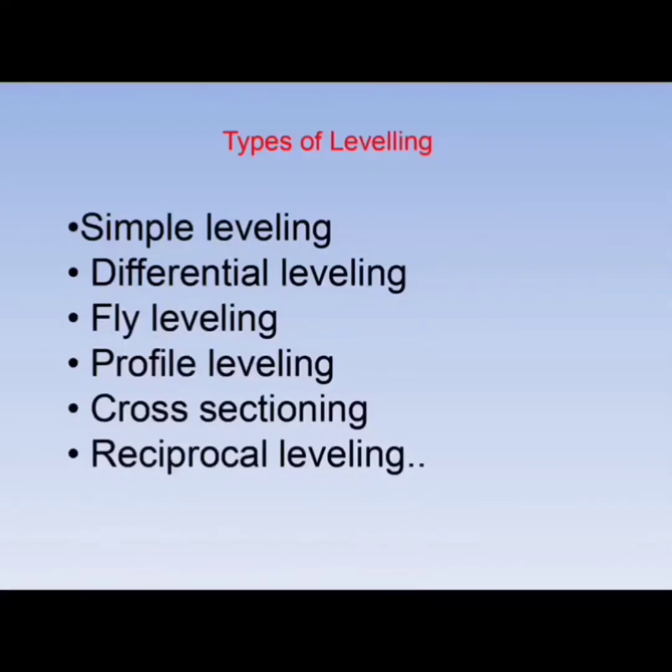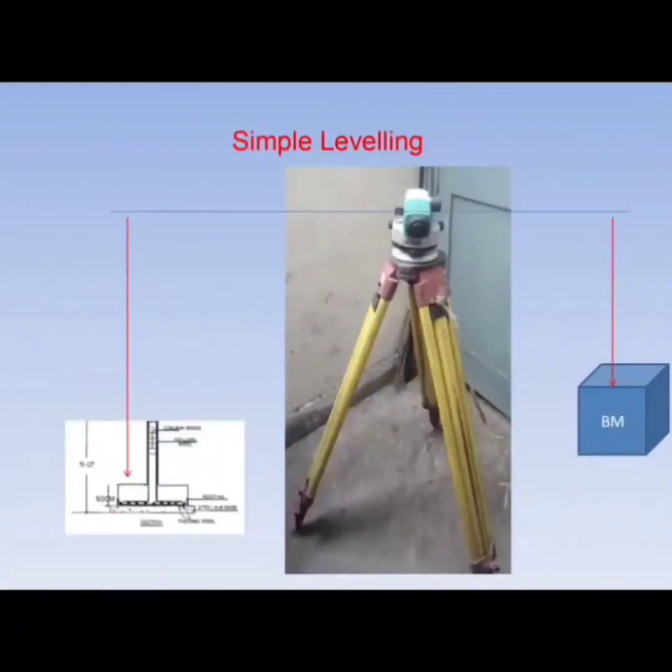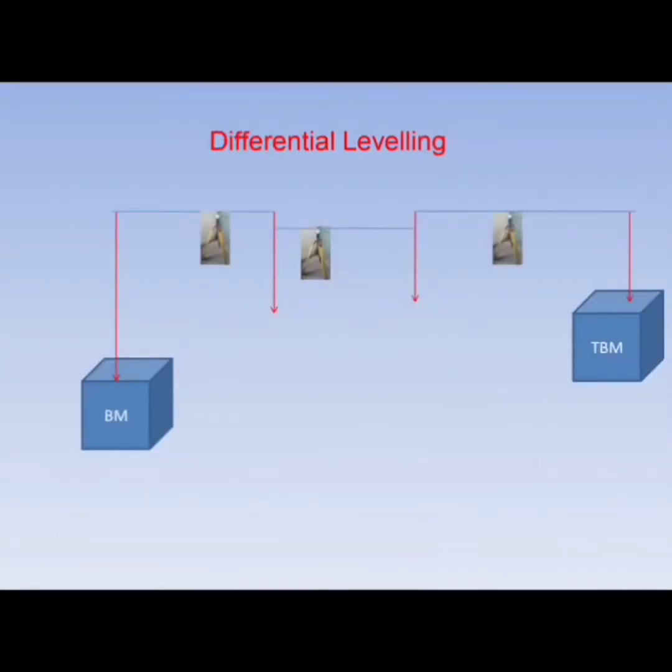Types of leveling: simple leveling, differential leveling, fly leveling, profile leveling, cross sectioning, reciprocal leveling. Simple leveling is done to know the difference between two points. Differential leveling is done when two points are away from each other.